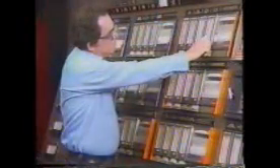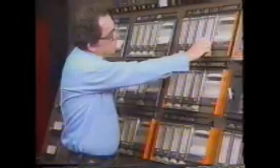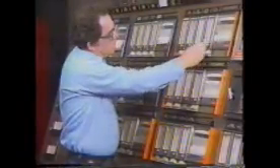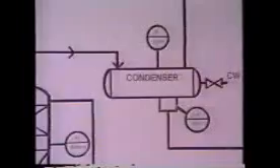The inside operator also sets the level controller on the condenser leg to the level prescribed by this system's startup procedure and places it in automatic. Once the overhead product in the condenser leg reaches that prescribed level, the level controller will automatically open the overhead product takeoff valve.